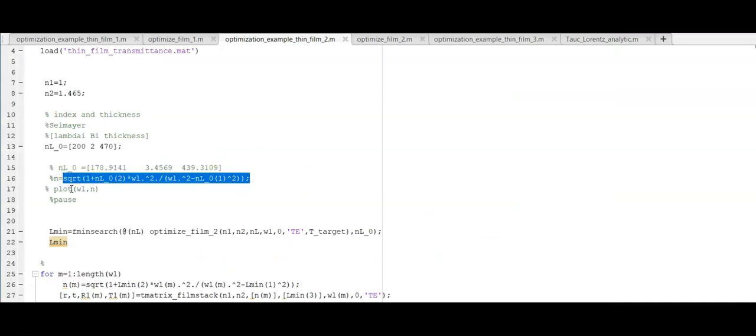And this model is now used in MATLAB, and as initial values we have the resonance wavelength, and that needs to be outside the measured range, so we select about a 200 nanometer resonance. Then the constant b we select as 2 and take the thickness from the previous fit of 470 nanometers.